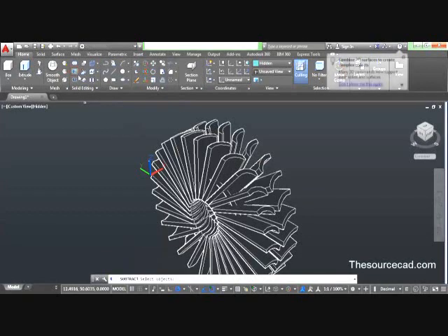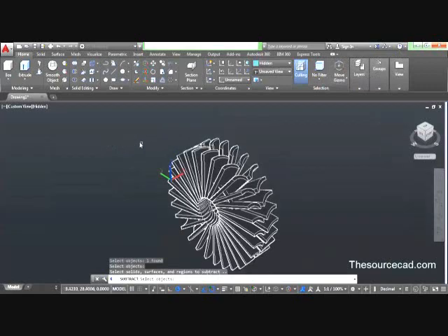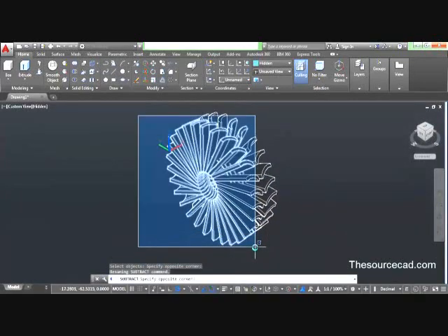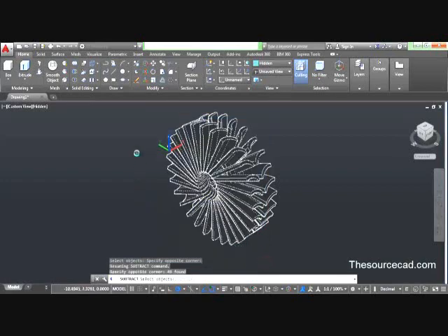Now select subtract tool and now make sure that you select this tire and press enter, and now select all these arrayed objects which we have made. So select as many objects as you can in a single run, and yeah, this seems good to me, and press enter.